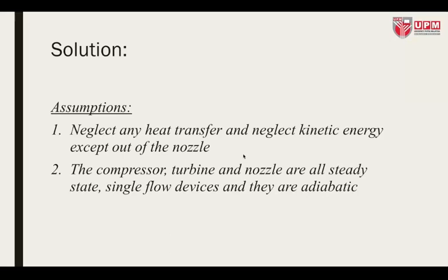In any propulsion problem, assumptions are made basically to reduce the complexity. Of course, the problem is real, but in order for us to approach it in a more appropriate way, as a first guess, you may provide a few assumptions. Among other assumptions, we may neglect any heat transfer and also neglect kinetic energy except at the nozzle exit. All right. So that's the first assumption we make.